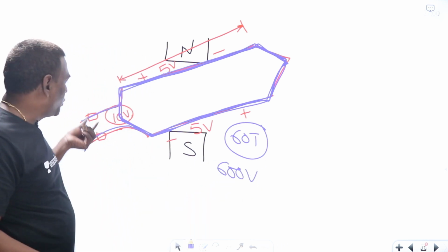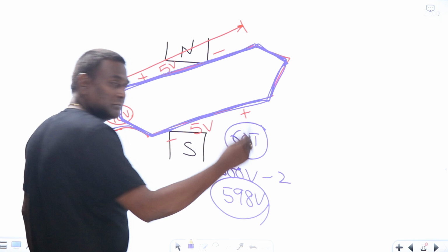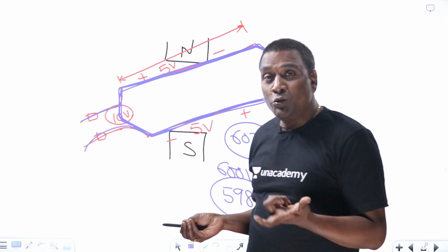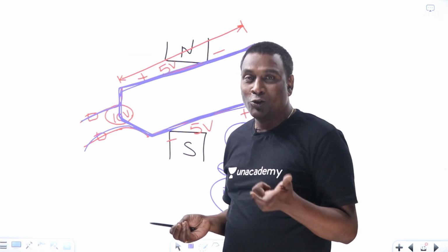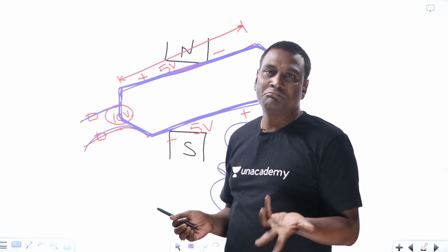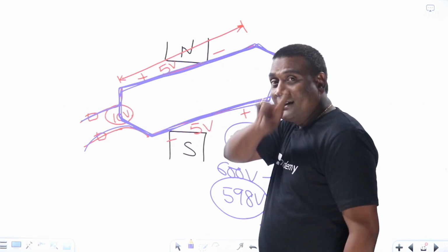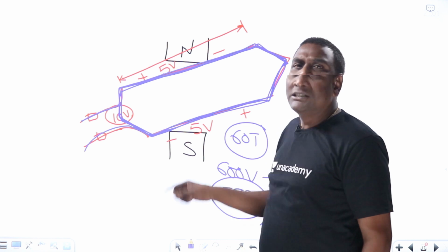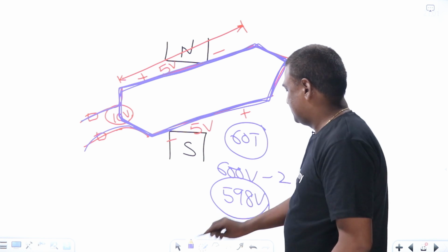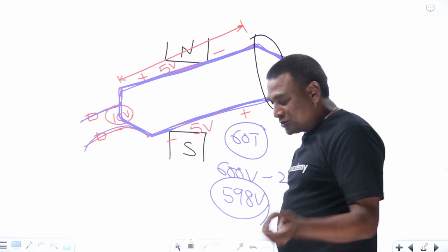Maybe if you want to take the voltage drop for 2 brushes into account. So the point is very simple. In order to produce a significant amount of voltage, homopolar is not possible, at least 100 volts. But a significant amount of voltage can be produced in the heteropolar structure, because of the back-to-back connection. So simple.